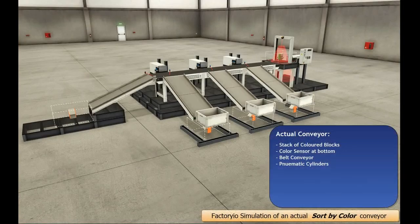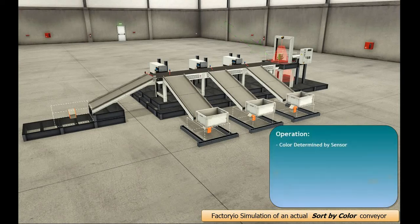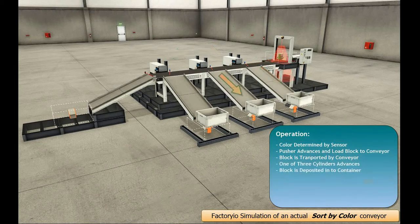What I have here is a simulation of the conveyor system we built in one of the labs. A stack of colored blocks is loaded into a tube at the start of the belt. At the bottom of this tube is a color sensor. The sensor sends a signal to the PLC based on the color of the block at the bottom of the stack. Once the color has been determined, a pneumatic cylinder is used to push the block forward onto the conveyor. The motor is then turned on and the block is transported by the belt. One of the 3 cylinders is then used to push the block into the bin designated for that color.